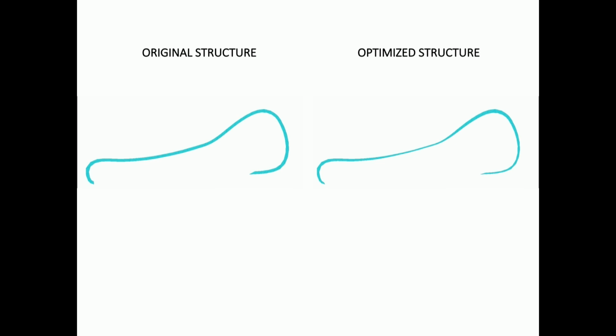If we read papers that describe the structure in practice, they mention that the average depth of the space frame throughout the museum structure is 1 meter. So when we ran the optimization analysis, the joints were free to move from 0.5 meter to 10 meters. So they had quite a lot of freedom, and there were many possibilities to find improved solutions.